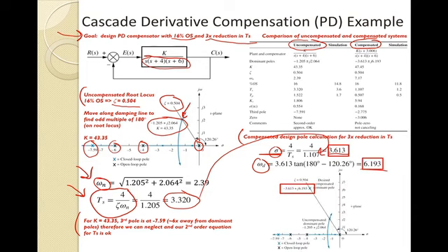I also want to remain with that overshoot, so I'm on the same line. Originally I had my dominant poles at minus 1.2 plus j 0.06, but now those poles are migrating up that same damping line, same overshoot. That will be our desired compensator pole location. You can see the uncompensated system down below for reference.